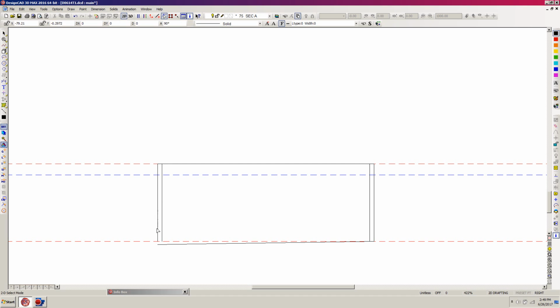Now I want these two wall lines to come down to this sloping floor. So I'm going to hit E, and that trims my wall line to the floor line, and I'll hit E again, and it trims my inside wall line to the floor line. That accommodates the sloping floor really nicely. And what we need to do next is put some plates on this wall.